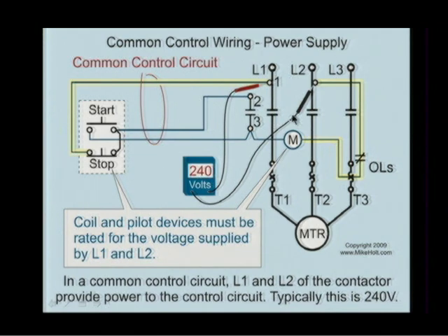Okay, so if I close these 3 main contacts, this motor will run. I come off of terminal 2 and go through the overloads in series with the overloads, and I bring power over from terminal 2 over to the motor. Now, in reality, voltage is actually traveling to the coil. Voltage actually is traveling through the coil over to this one point right here. So really this is one phase voltage and this is another, right? So right between this point and this point right here, I should measure how many volts? 240, right? 240. So that's another way for troubleshooting.